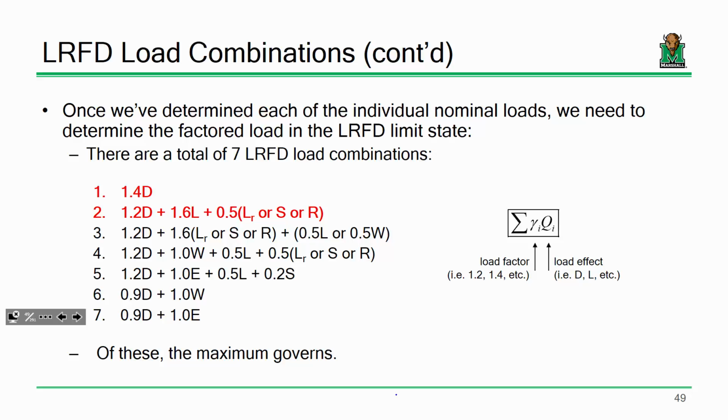There's a really weird effect that can happen in structural engineering called ponding. Did I mention ponding at all last semester? Okay, so ponding is a really strange effect that I thought I'd mention. If you have rain collected on a roof, that is a load on the roof. It has a certain weight and it's applying a load to the roof. What can happen is, let's say you get to a point where you permanently fail a component of the roof because of that excess of water.